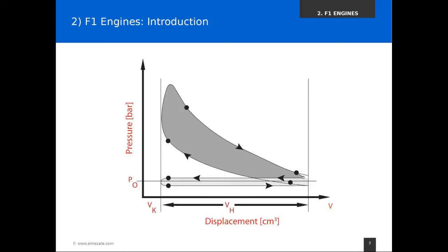And then once we've reached the right corner, the piston is all the way down, and now we have to change the gas. So what we have inside our combustion chamber now is just burnt fuel, a mixture of burnt fuel and air, and probably no oxygen. So we need to push that out. That needs to go into the exhaust and then basically into the environment.